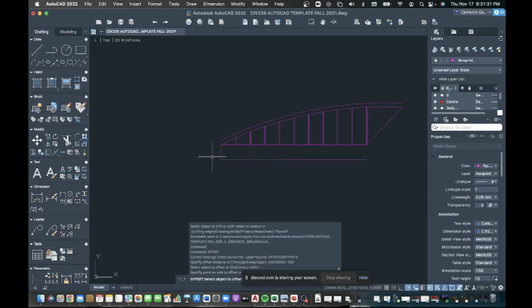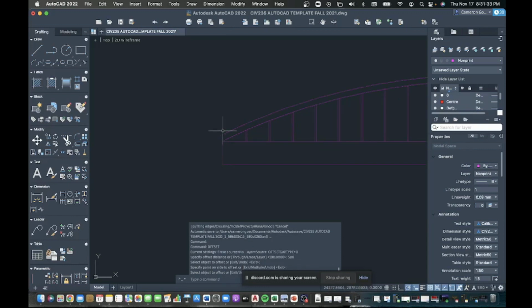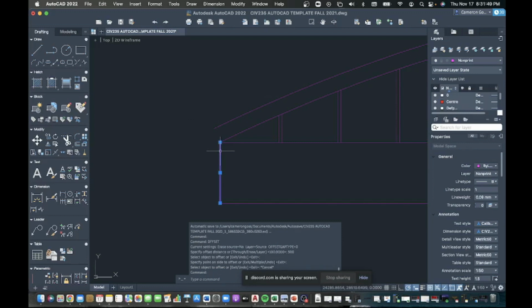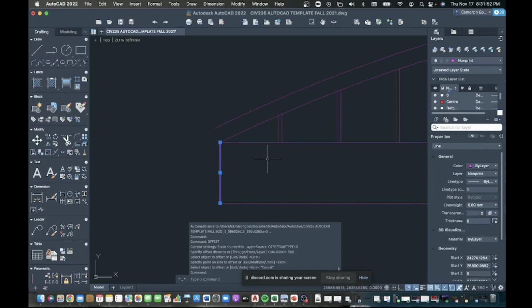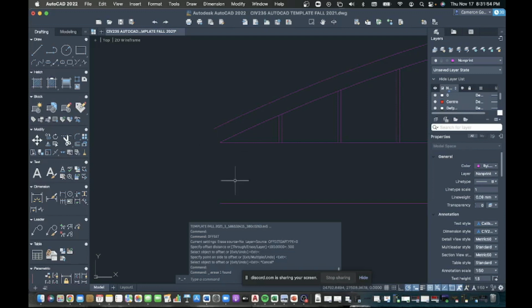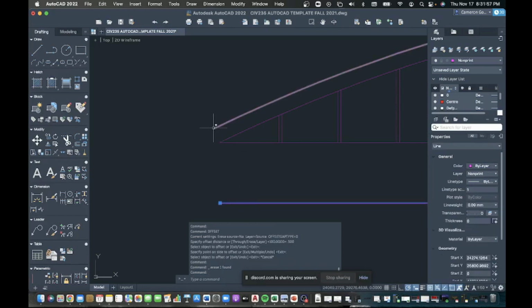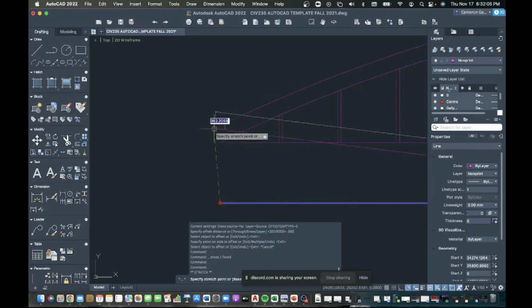So what we've got here is a little discontinuity. What we can do is fix this line up here. We extend. I might as well get rid of this. We're going to delete this line just by clicking delete, and I'm going to extend this line over to the edge of this point of the arc here, and I'm going to do that by taking the point here, hovering over this, and then that will allow me to snap to the end of it.